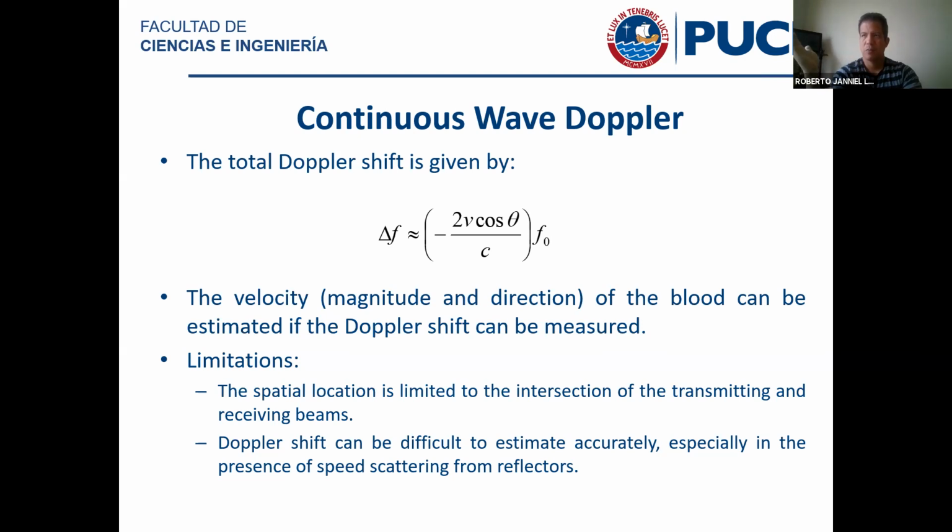But you're basically transmitting, even if you transmit a purely sinusoidal signal, so you have literally a continuous wave, and the spectrum is a delta function, the spectrum of the signal that you're going to pick up when this very long harmonic signal interacts with the blood flowing is going to have a broadening. It's going to have a bandwidth.